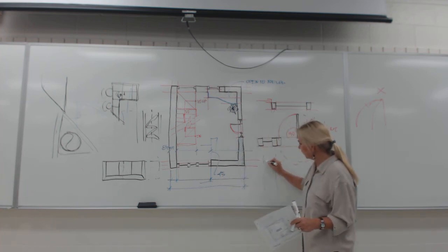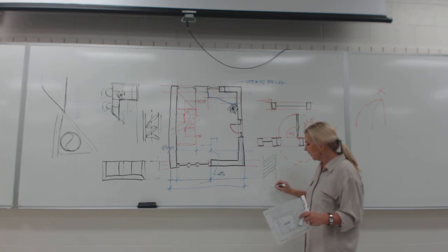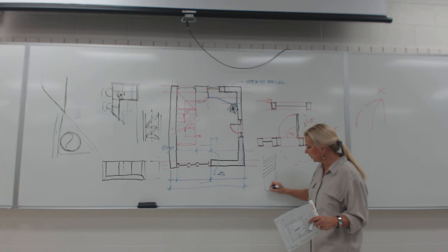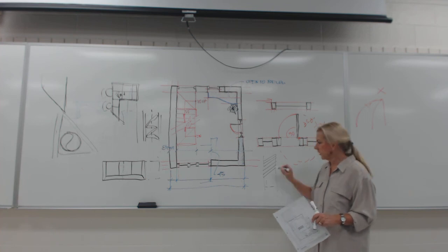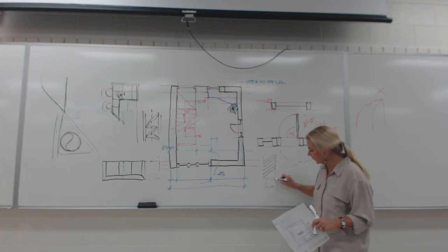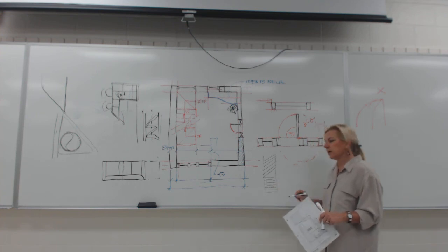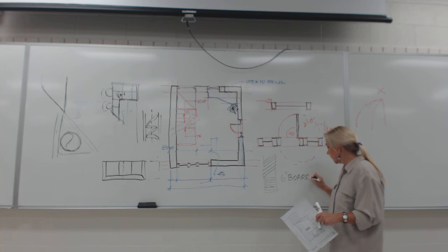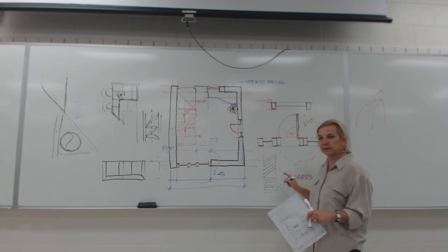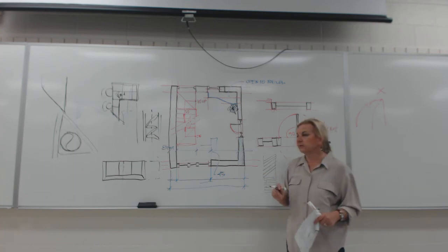So what can you do? You could have cedar boards going on 45 at 6 inches apart. The only way that they would not run is probably the structure was this way. So yeah, they could go any way. The box is all the way around, so I would probably put boards this way, 6 inches apart. 6-inch boards would be better, less drafting, and they're more standard than 4-inch, okay? Which we had on our previous drawing.